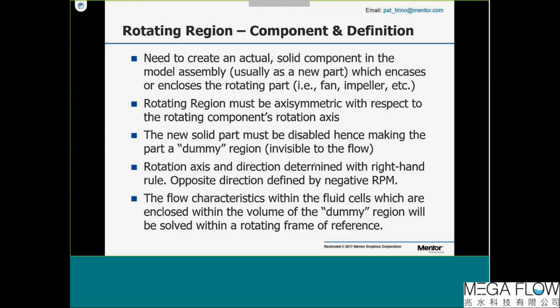That'll tell us what direction that fan should be rotating. The flow characteristics within the fluid cells, which are enclosed within the volume of the dummy region, will be solved within a rotating frame of reference. Again, that dummy region is how EFD knows to calculate those cells using a rotating frame of reference.